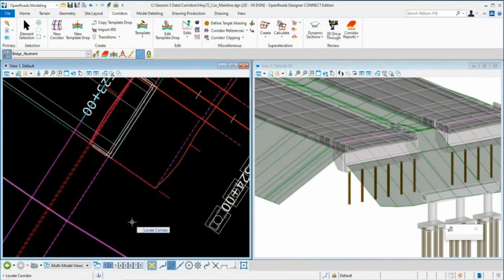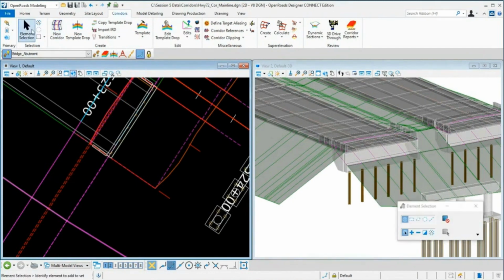First way, we're just going to utilize a 3D point, some geometry, and some linear templates to accomplish it. So let's take a look at how we would do this. Okay, so I'm going to be working in this corridor here. One of the things that I did with my template is I had this 2 to 1 slope line being projected up here onto my main line.